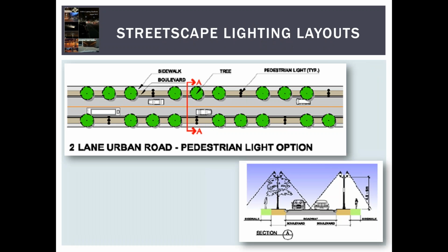For the streetscape lighting layouts, typical lighting layouts are shown in this figure from the FHWA Lighting Handbook for 2-lane roads. Pedestrian scale lighting may provide the required level of illumination for the street and the sidewalk together. However, if this does not provide the required results, for example if the roadways are wider, pedestrian scale lighting will typically have to be supplemented with taller overhead lighting.